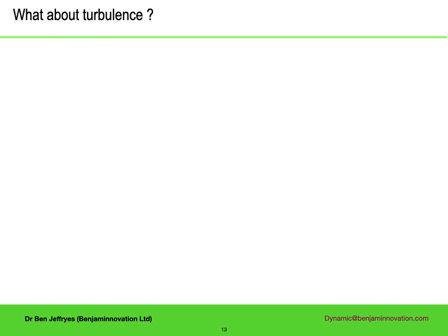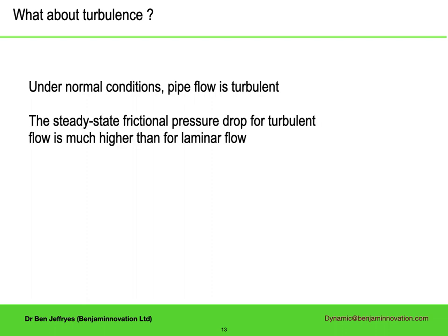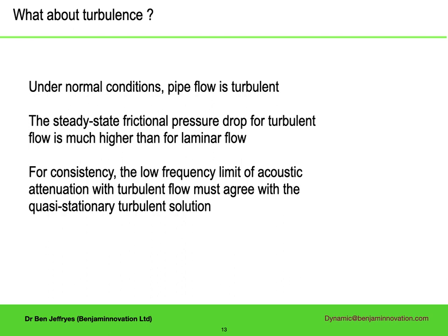It is not at all clear, however, how this applies to acoustic attenuation inside drill pipe while drilling, as the flow in the pipes is not laminar but highly turbulent. This has a much higher steady-state frictional pressure drop than for laminar flow. The low frequency limit of acoustic attenuation has to agree with a quasi-stationary turbulent solution, not a quasi-stationary laminar solution.